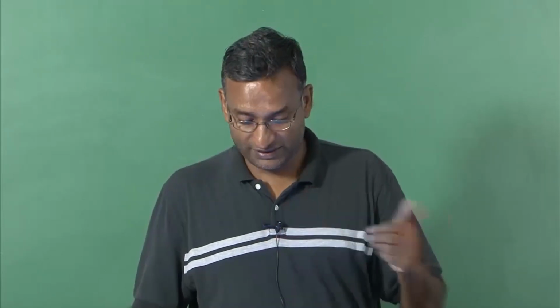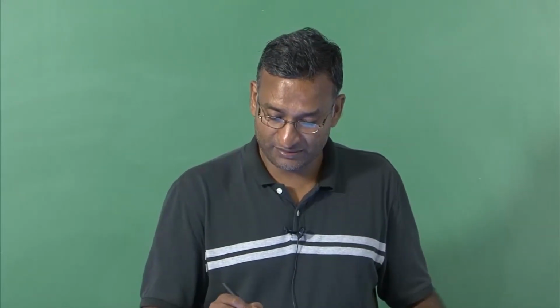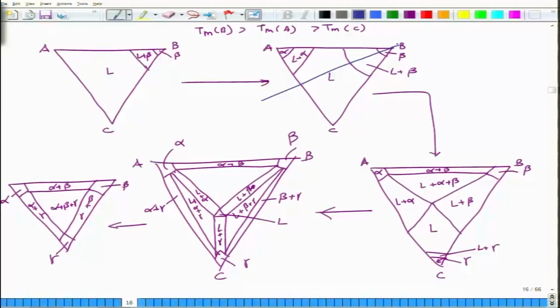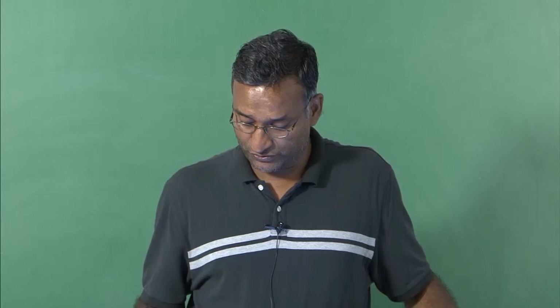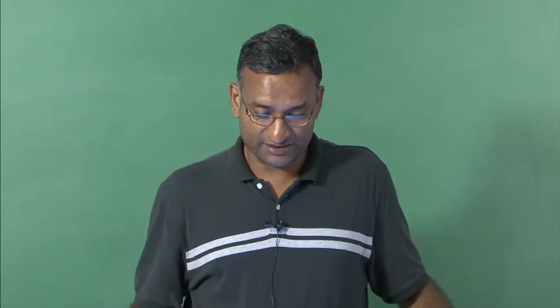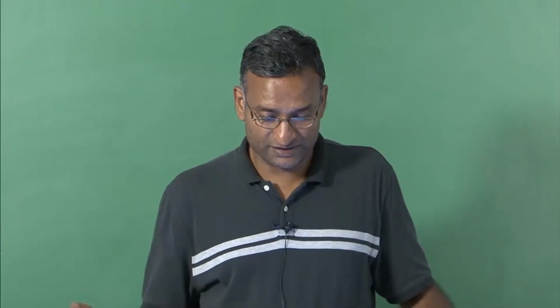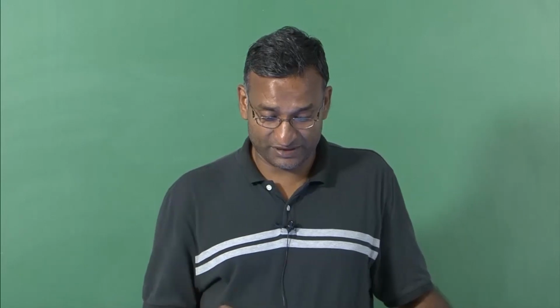So again, by drawing the tie lines, the vertical lines, horizontal lines, and by taking the isopleths, you can look at the evolution of phases. If you take, for example, the isopleth at a particular point starting from B, you can look at the evolution of phases as a function of temperature for fixed B and let us say 50% A, 50% C, and you can do this for various temperatures to understand the phase evolution. And then we looked at certain applications, uses of ternary phase diagrams. They are useful for refractory applications and they are useful for stainless steel applications.